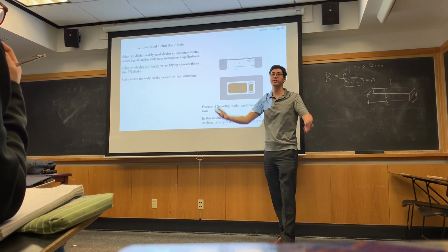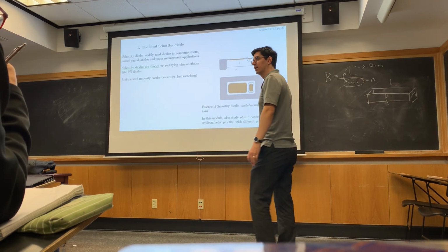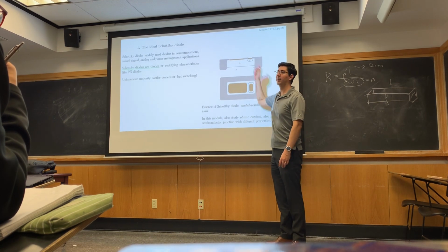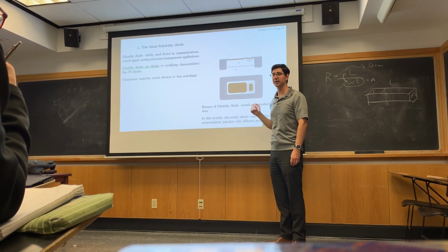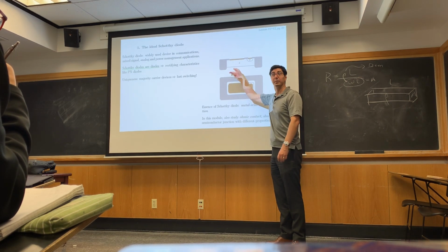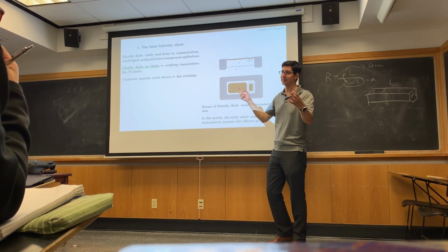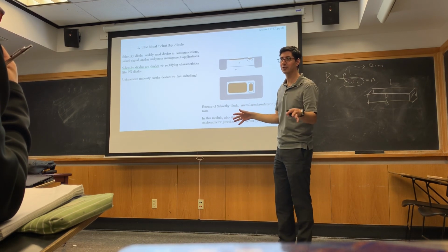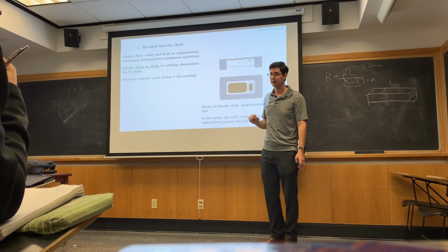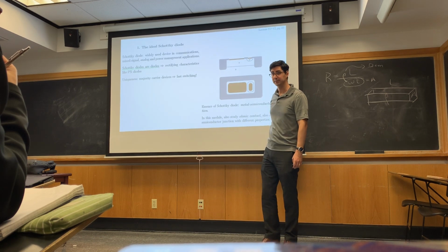Why? Because you should already see a PN junction can rectify, right? It provides a barrier to current flow. If I forward bias this PN junction, can it conduct? Yes, it can, if I forward bias it. So we better not forward bias this PN junction. Keep that in mind, right? And that's how we would design our circuits. We could never have it where this PN junction's forward biased. But as long as we keep this neutral or reverse bias, we're fine.